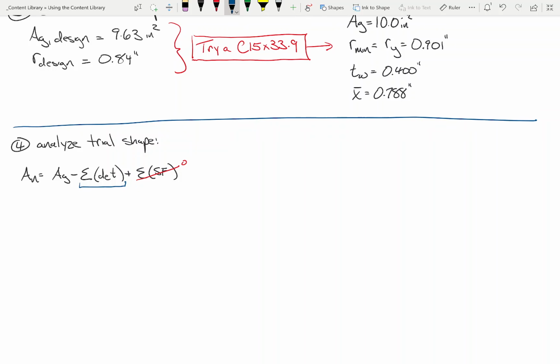I guess my question is, how many of those? Two. There's two bolt holes. So my expression, and what's the thickness, by the way? But it's the thickness of the web. That's sort of what I was getting at, is that our net area is going to be the gross area minus 2 diameter times the thickness of the web, which is going to be...